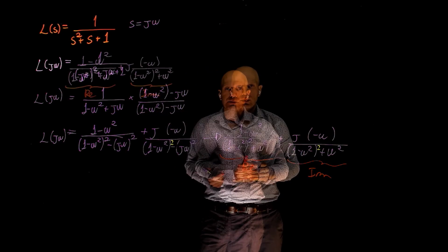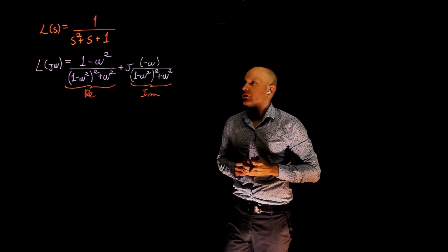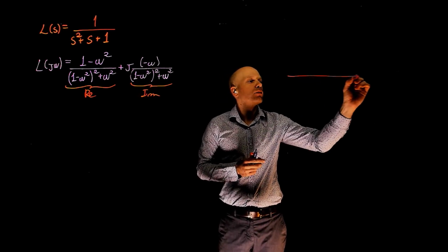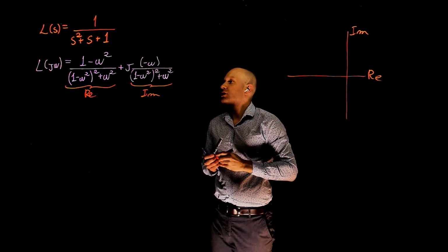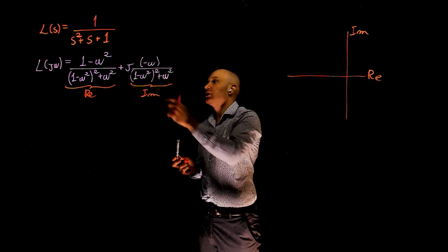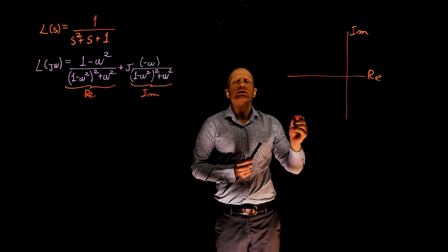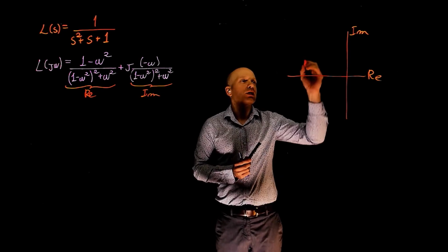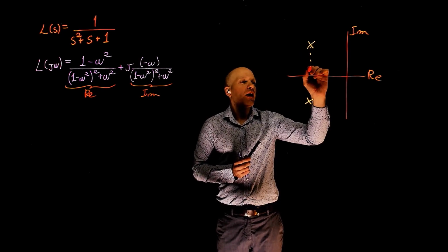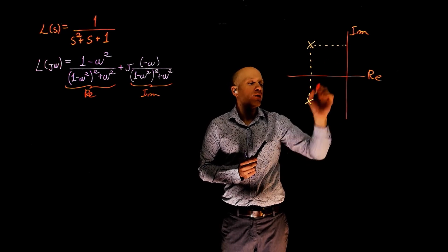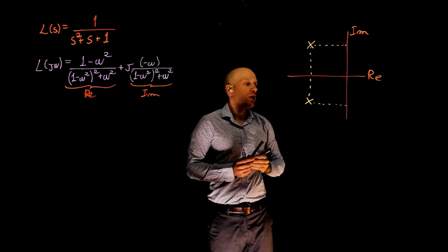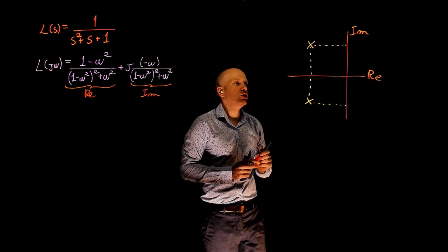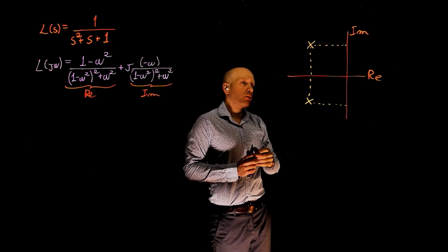on the Nyquist plot. To evaluate the phase and the magnitude of the transfer function, we can place the poles and zeros of this transfer function on the S-plane. This transfer function has 2 poles and no zeros, and you can see that these poles are complex conjugate numbers. The damping ratio is less than 1, so they will be placed on the left side of the S-plane. They have the same real part, and they have conjugate imaginary parts. If this is aj, this would be -aj. Now we can put in our points of interest.